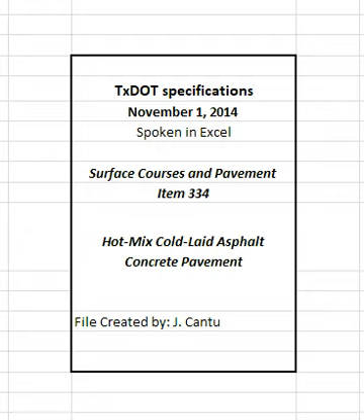4.4.2 Tack coat. Clean the surface before placing the tack coat. Apply tack coat uniformly at the approved rate unless otherwise directed. The engineer will set the rate between 0.04 and 0.10 gal of residual asphalt per square yard of surface area. Apply a thin, uniform tack coat to all contact surfaces of curbs, structures, and joints. Prevent splattering of the tack coat when placed adjacent to curb, gutter, and structures. Roll the tack coat with a pneumatic tire roller when directed.